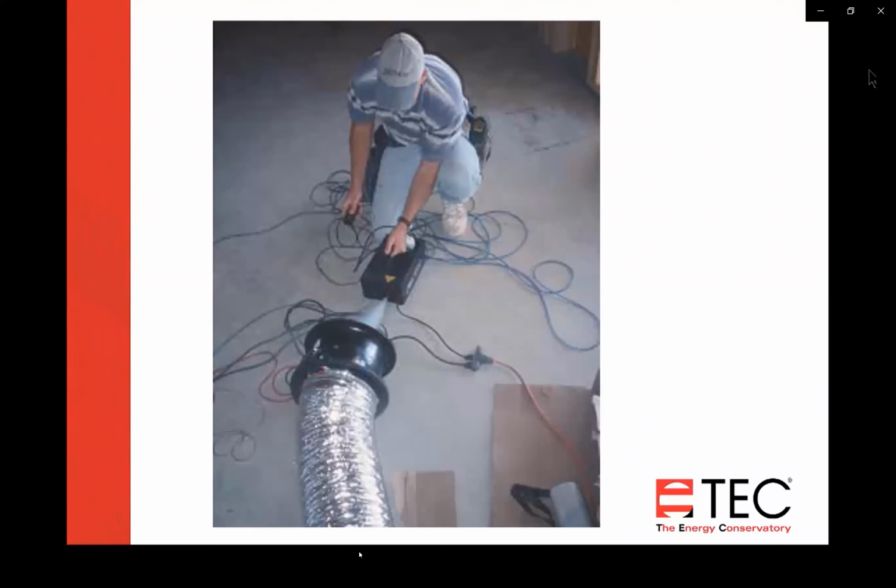It's best for sure to use open fan, so you're turning on the duct blaster fan too and pressurizing the ductwork slightly. You want to use open fan so you're not concentrating that fog right over the flow sensor. You don't want to be blowing directly onto the flow sensor or the motor. You want it pointing off to the side of the duct blaster fan a little bit, so it's not coating the fan with smoke.